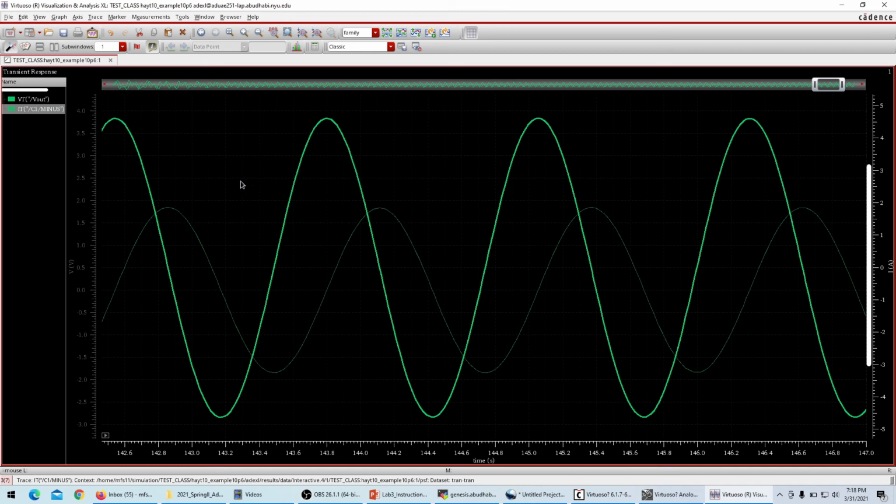So I have exported these two plots in a new window, and I just took the voltage through the capacitor, and later I selected the current. So I appended the current on the plot. Now looking at the phase shift, have a look at this plot. This is the voltage, and you see that this voltage is reaching its peak at this point, and this is exactly the point where the current wave is starting, the current through the capacitor.